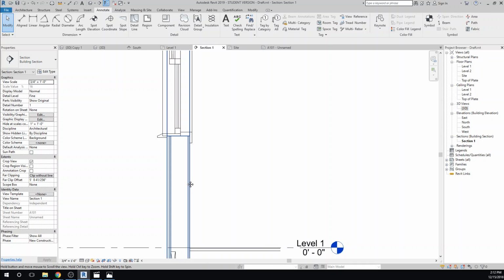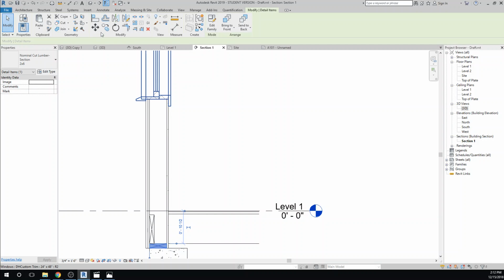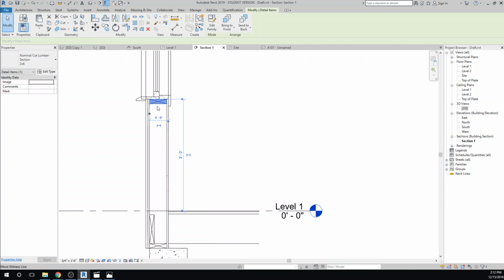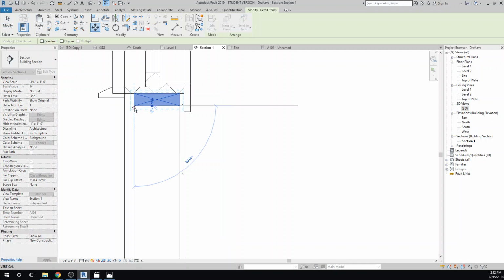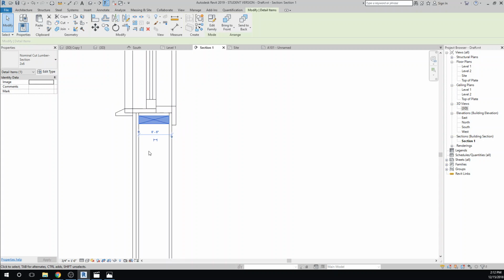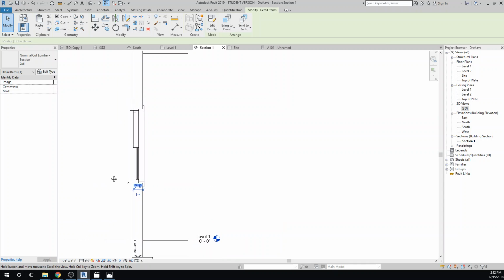And we're going to do a lot of the similar things here. So I'm just going to do a few copies and move. I'm going to grab this, and copy and move it up, because we would have this piece of lumber sitting underneath the window, except I'm going to give it a little bit of a gap. I'll come down a 1/2 inch. There's usually the idea of shimming between the rough framing, and we're going to do that up above too.